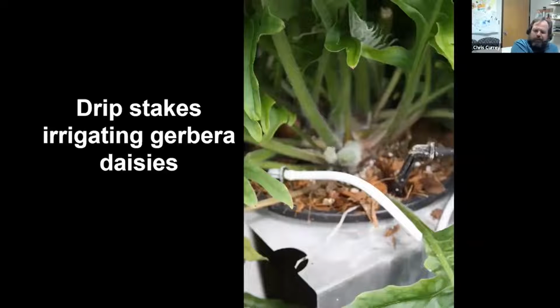Why do we have 2 drippers per plant? Well, in some instances, you can really just think of it as insurance. When we're working with hydroponic systems, we're delivering a nutrient solution that's got salt dissolved in it. When that salt dries on our irrigation equipment, sometimes it can clog emitters. If we have a clogged emitter, we won't get nutrient solution delivered to our plant, and if that happens, we can have plant death. By using multiple drippers per plant, that can be an insurance policy just in case you ever do have a clogged emitter.